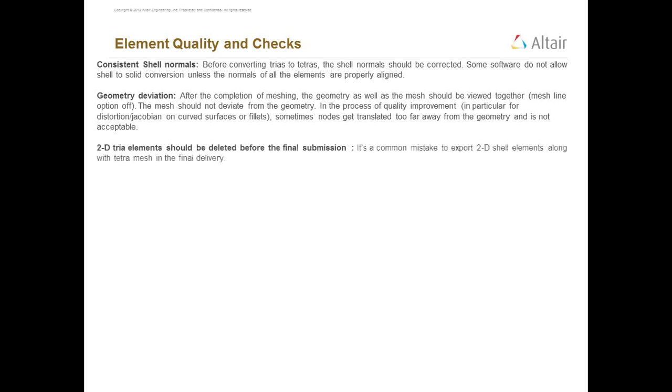2D tria elements should be deleted before the final submission. It's a common mistake to export 2D shell elements along with the Tetra mesh in the final delivery.